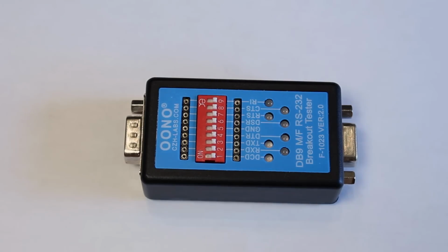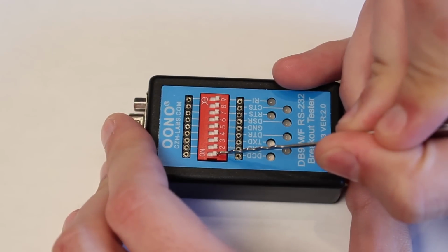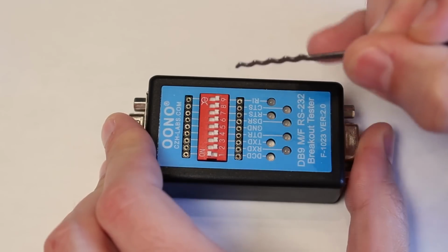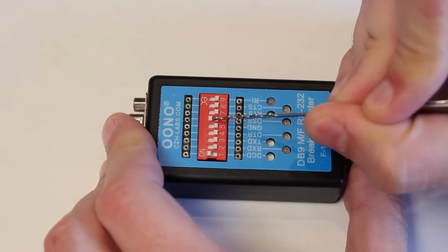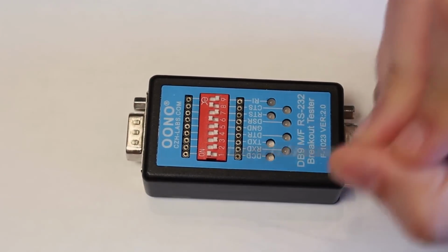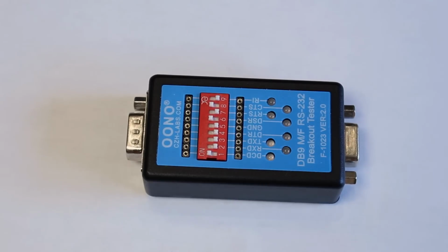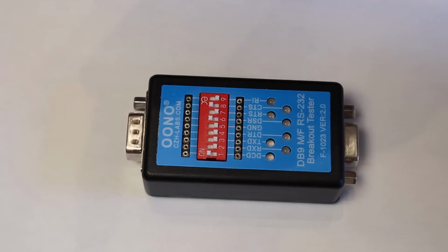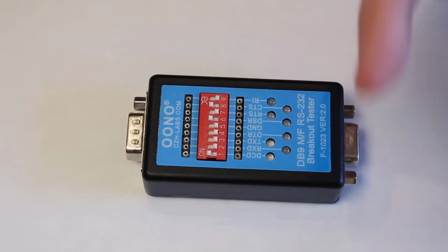And we actually want 3 of our 4 signals to pass through. We want ground, which is on pin 1. We want receive, which is on pin 6, and transmit, which is on pin 8. But the CTS signal, which is on pin 2, won't pass through. And the terminal is going to be on the male side, and the mux is on the female side.